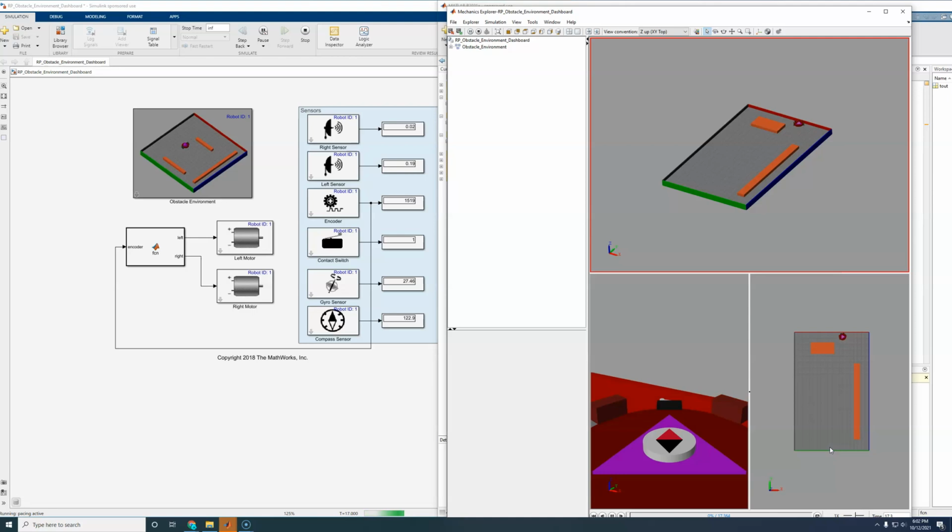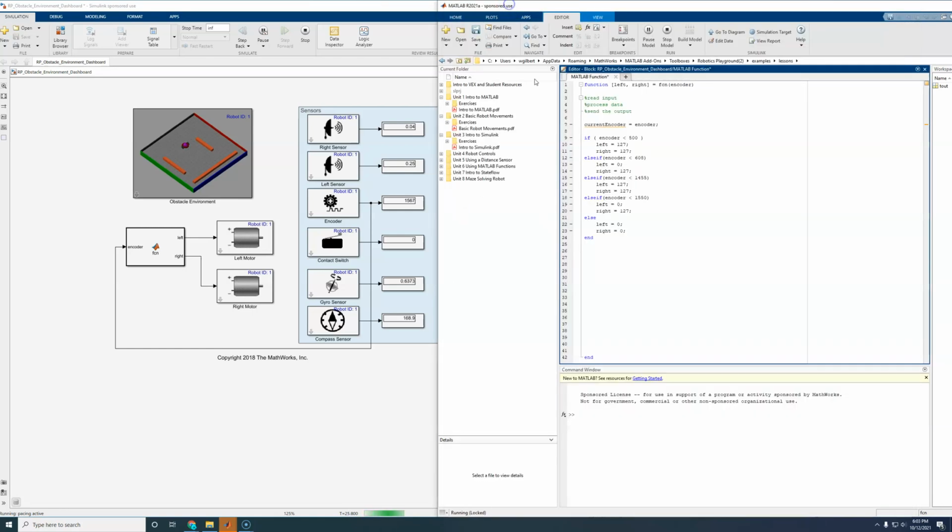Okay, and we hit the wall again, so I need to shorten it a little bit further, and we overturned by just a hair, but that could have been related to hitting the wall as well. It's hard to tell. So let's back that down to 1440, and we'll need to bring this one down to 1440 plus 100 would be 1540, and let's bring it down 5 more from that, so 95.